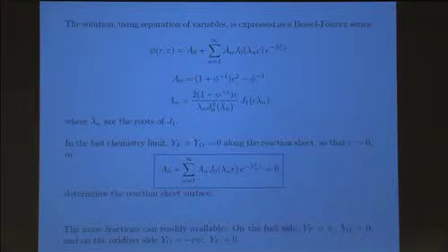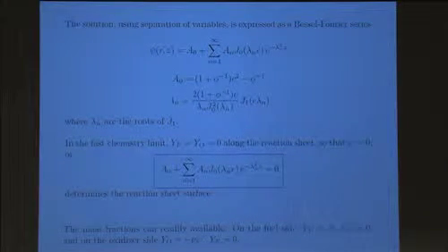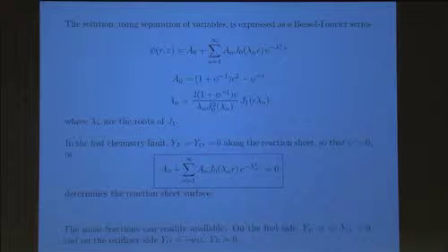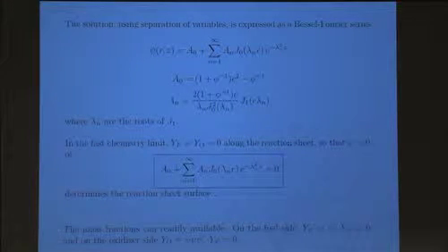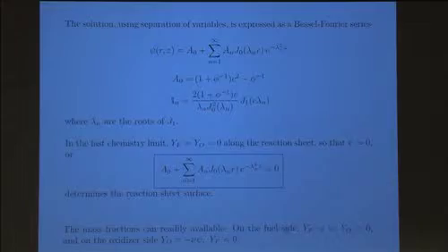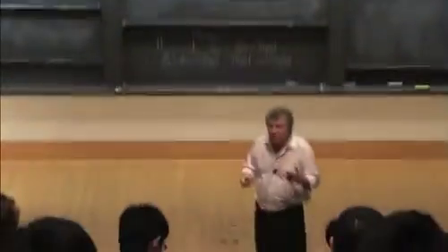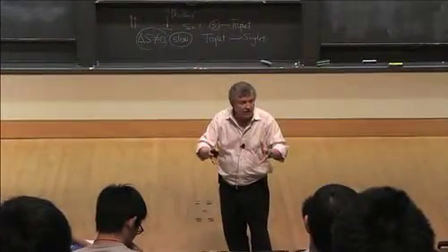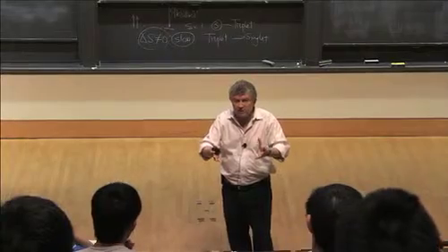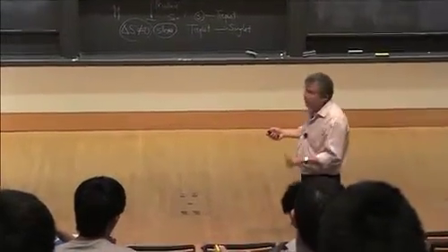Now, if YF and YO are equal to 0, which means psi equal to 0, the solution is just a relation between the radial distance and z. So it's a surface in space, right? And that surface is the flame sheet.